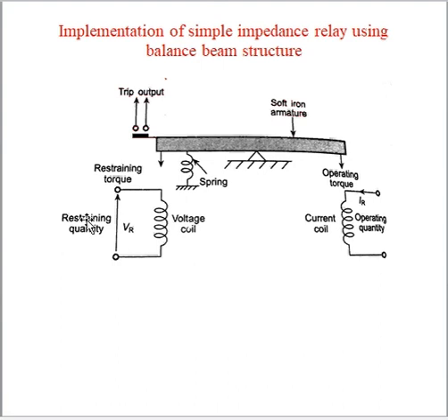If a fault is there, what happens: current will increase and voltage will decrease, because the impedance is very low, so the current is more and the voltage decreases by comparison. Then, with more current, this will attract this one, because here we are connecting a spring. This comes down and this goes up, then the black colored knob will touch these two points.